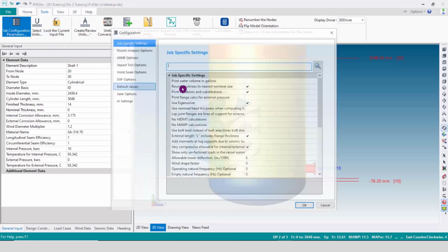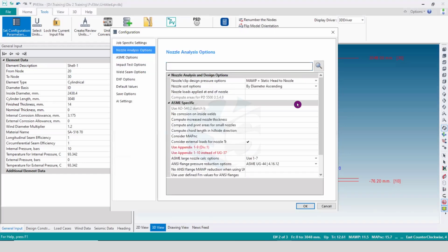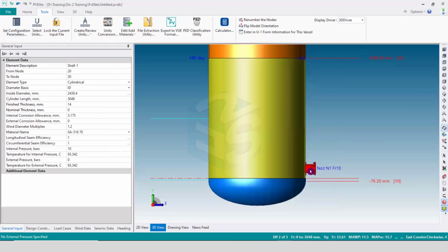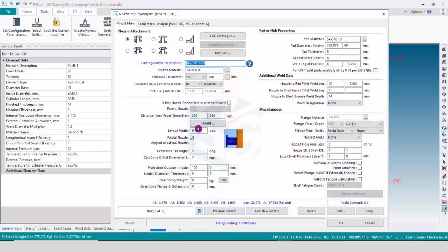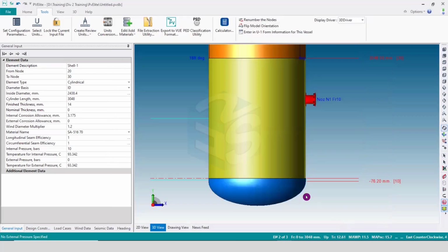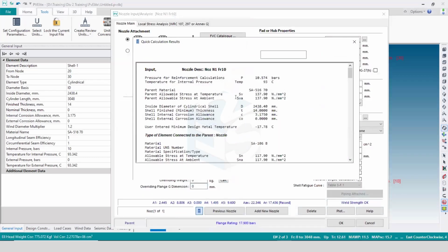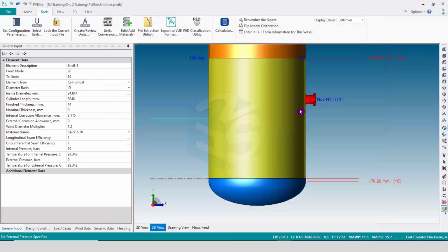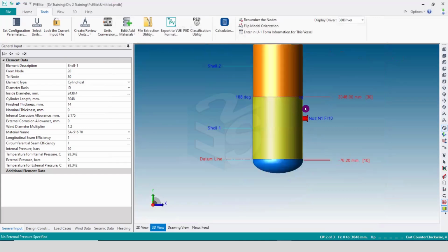Now, there is a third option. So if I shift this nozzle to the top, let's say I'm having it at 2500 or let's say 2000 elevation. So earlier we have seen 10.746 was the pressure considered. Now what is the pressure? 10.574. Why so? Because the nozzle has been shifted to the top. So till this point, whatever the static head is there, that has been considered.